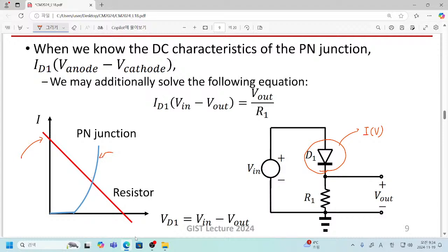Well, if you change, for example, the dose of your ion implantation, or if you change the temperature of your dopant diffusion, then what will happen to your PN junction IV characteristics? This kind of information cannot be obtained solely from this SPICE model.